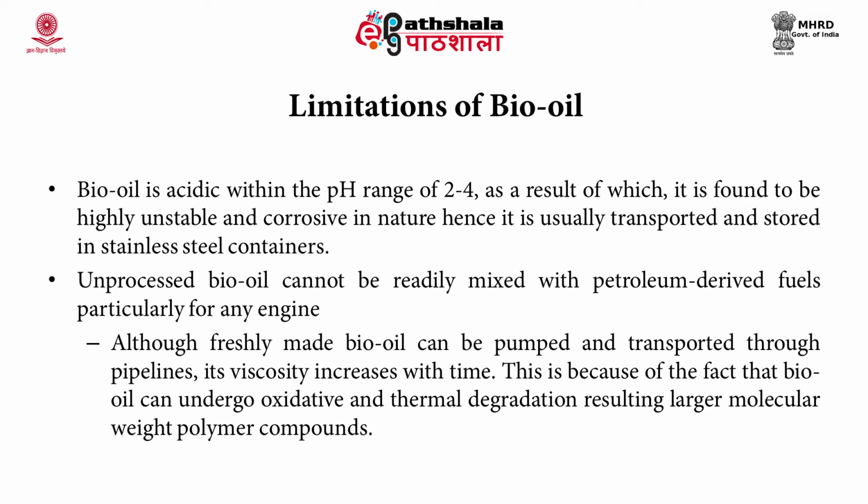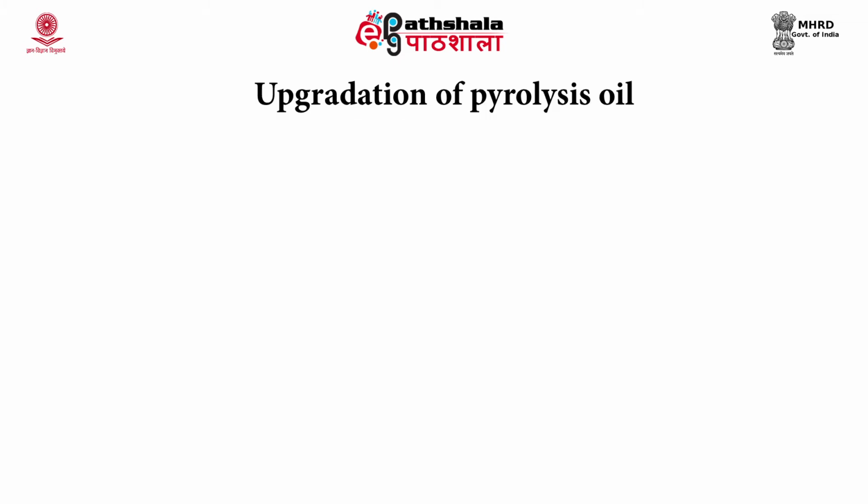So, it is also a problem in using it as a fuel. Because bio oil can undergo oxidative and thermal degradation resulting in large molecular weight polymer compounds, unprocessed bio oil cannot be readily mixed with petroleum derived fuels, particularly for any engine. So, an upgradation of pyrolysis oil is required. The bio oil contains high proportion of oxygenated compounds, viscous, acidic in nature.